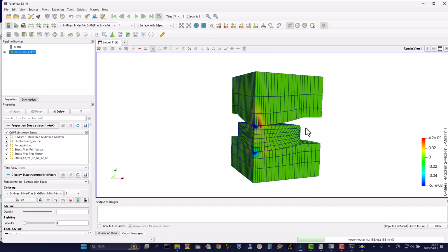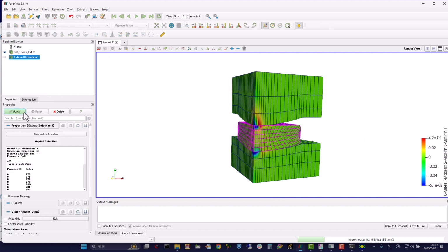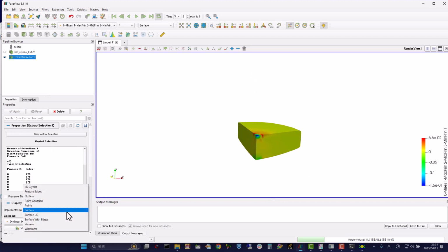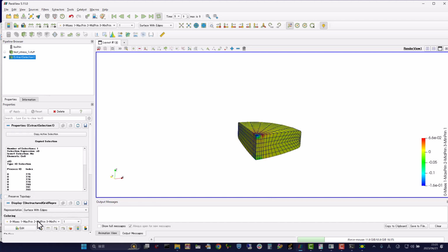It is also possible to take out only the glass. Since this is already a function of ParaView, although it would be better for you to investigate it yourself, I will briefly introduce it for the glass part. Select some of the elements first, then keep pressing this plus. If you have selected up to the boundary, press the eject button, then press apply. You can only see it here. Over here, surface with edges, and if you run this here, you can only see the glass.